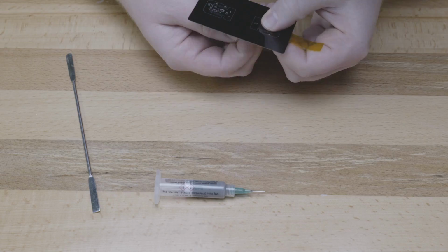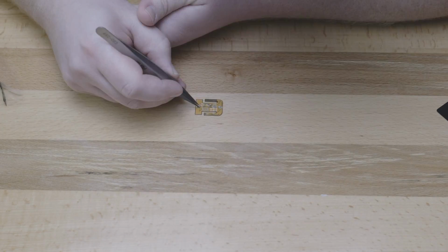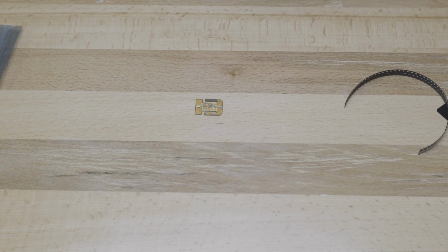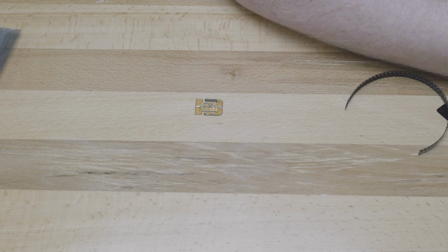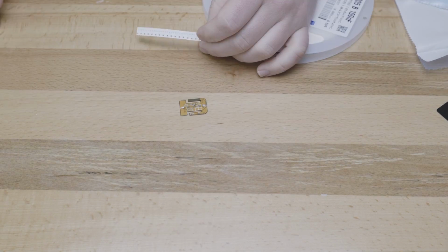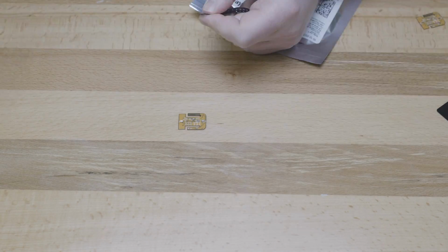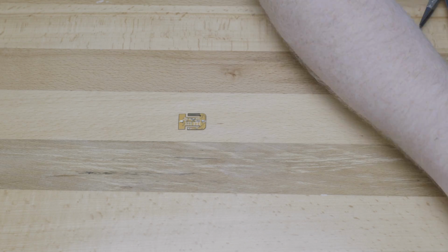So now, I just align the board to the stencil, tape it on, spread the solder paste in, all of which is easier said than done. I'm using bismuth-based solder paste here, which melts at a very low temperature, around 138 Celsius. I usually use SN100C for conventional soldering, but I find that this low temperature stuff works really well for LEDs, as those can melt pretty easily.